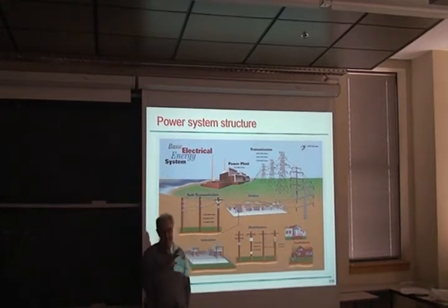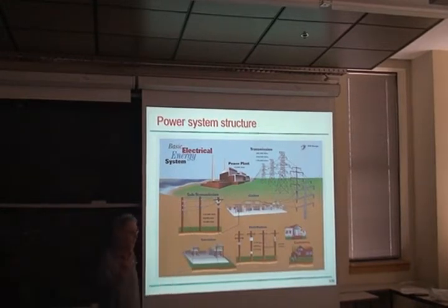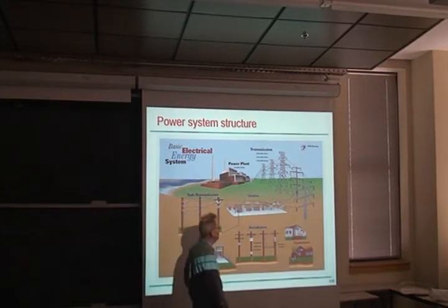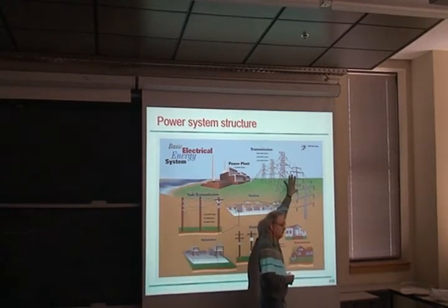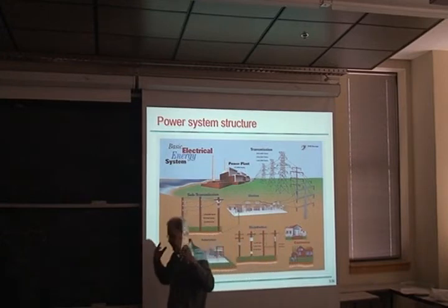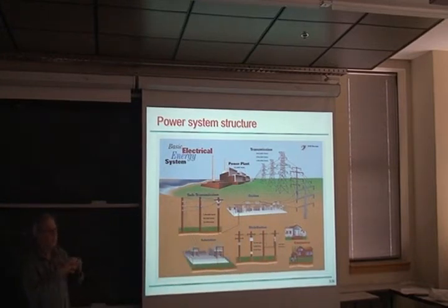If you're over on the west coast in Portland, there's an enormous amount of wind, and that's being put into the transmission network. So it's connected in at the transmission level because you're talking thousands of megawatts of wind capability, so you need the higher voltages to be able to carry that large amount.